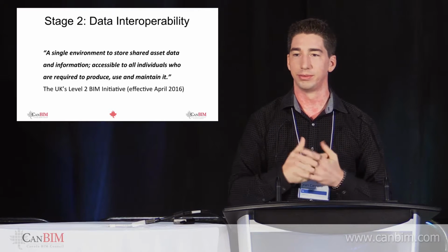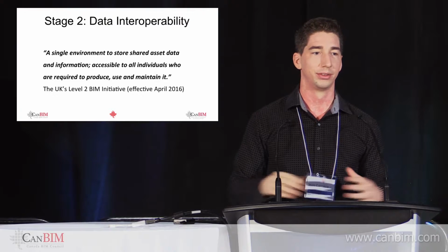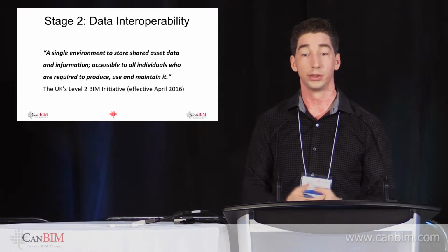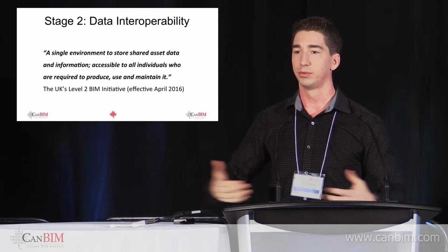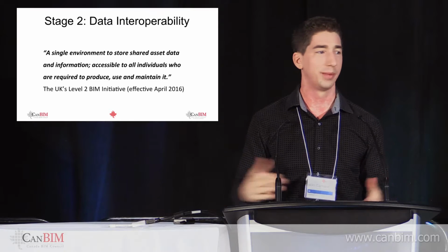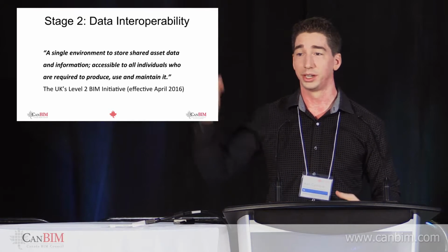So it's validating the information and making that information accessible to everyone, so that when the architect, who is not typically the guy that looks at the loads, sees the conference room, your loads are through the roof, and he's got a big VAV box, and there's no room for that box. It's too big. Well, maybe you got to change the lights. Maybe you got to change the windows. Maybe you got to start shading.